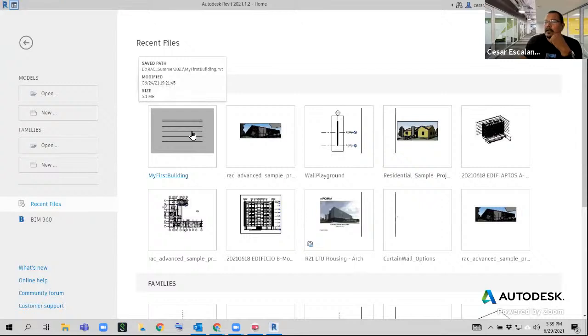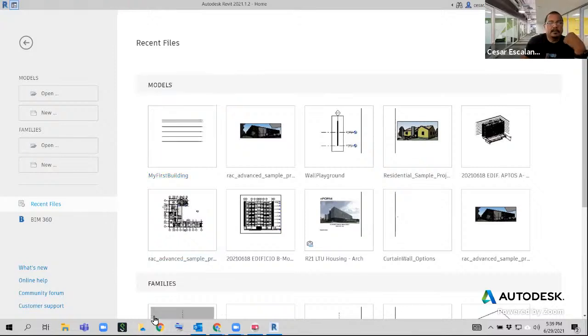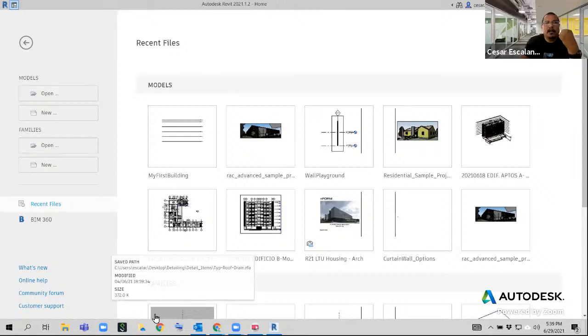We created a new wall from scratch, and I showed you how in every layer of material we need to assign a function. Function is associated with a priority number, and a priority number indicates Revit's way of understanding how the different layers connect in a wall intersection condition.